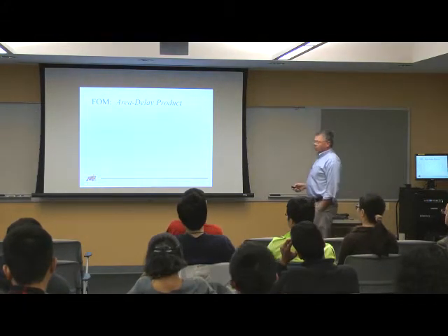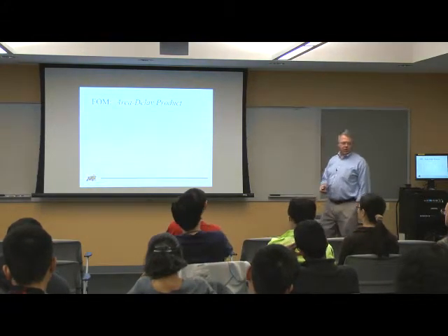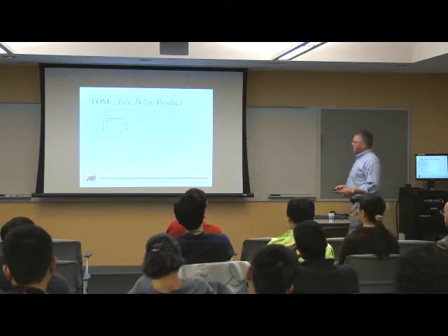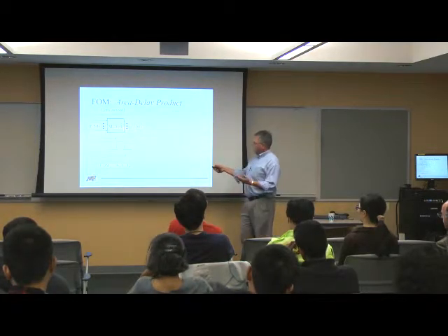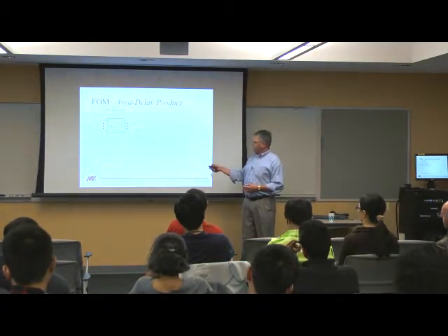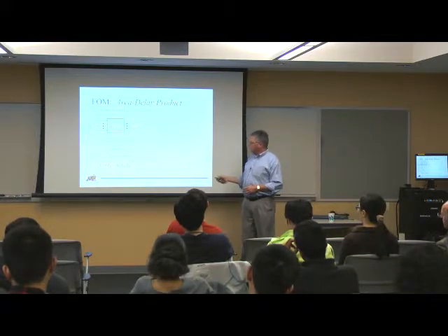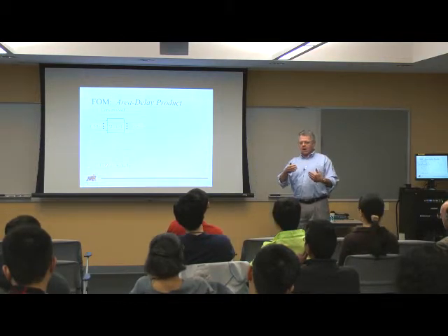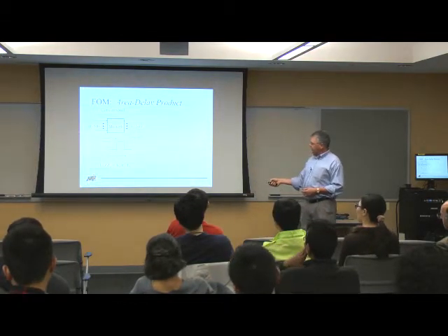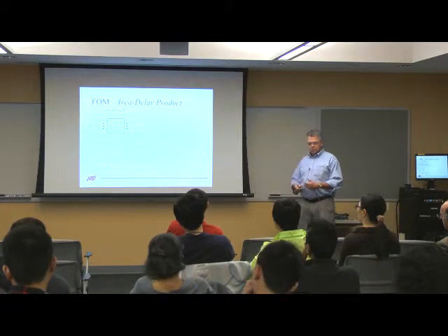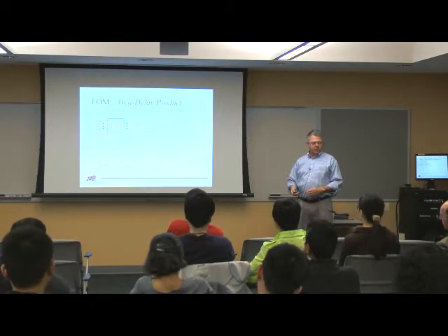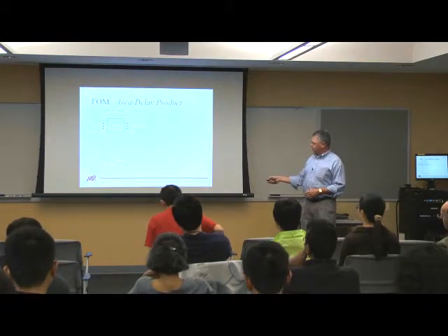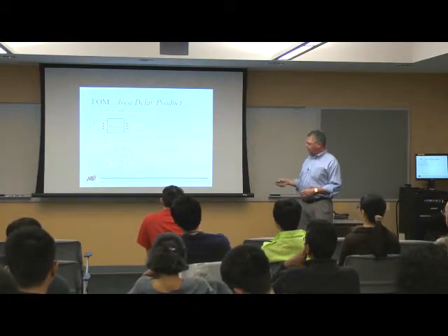Okay. So how well does this work? We're going to look for our figure of merit as area delay product. The idea behind area delay product is in a conventional implementation, say I've got a multiplier here, I've got m bits, multiply, and I produce m bits. I've got a critical path length, so that's the minimum delay through the circuit, that sets my clock rate. And then I have some latency, number of clocks to get through that. So maybe 2 clocks, 3 clocks, 4 clocks in order to get through that circuit. So I multiply the area times critical path by the number of cycles, the latency, and I get this figure of merit, area delay product.